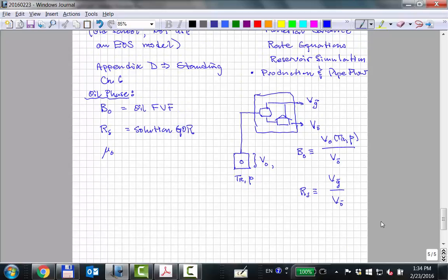So what we're going to do now is we're going to assume that this process is from our lab separator process. Now remember in chapter 6 we looked at four of these two-stage separators, right? And we found out the one with 100 psi G pressure gave the most oil, right? So that's our most efficient two-stage separator.